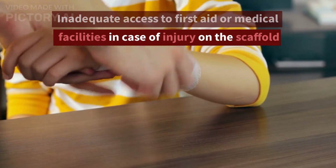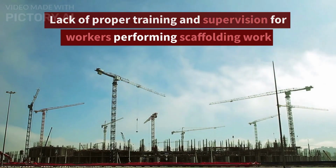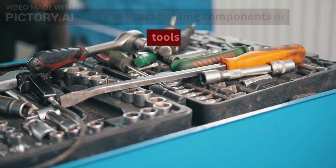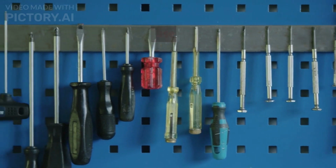Inadequate access to first aid or medical facilities in case of injury on the scaffold. Lack of proper training and supervision for workers performing scaffolding work. Incorrect use of scaffolding components or tools. Insufficient inspection of the scaffold before use.